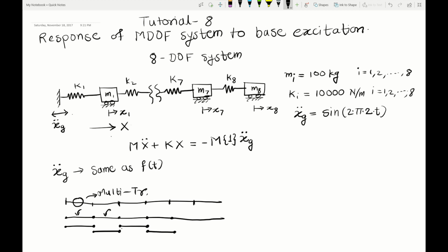What I mean here is that this is not like there is a vertical gap in between them. What I want to specify is that there will be 2 nodes at the same point, because each element is now separate. So once I do this meshing part, I need to make sure that I join these 2 nodes together, or merge these 2 nodes together. That I can do in the Salome interface, and I will explain it when we start the modeling part.